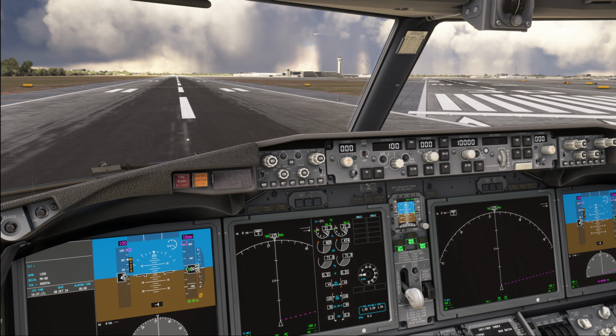For crosswinds greater than 43 knots, the thrust should be limited to a setting normally used for taxi. Note that this is particularly important as you are doing turns, as we're talking about the direct crosswind component to the aircraft. So you might have, let's say, 45 knots of wind down the runway, but when you are taxiing to the holding point, when you're standing in a 90-degree angle to the runway, then this is a crosswind, so you need to limit your thrust to a thrust setting normally used for taxi.